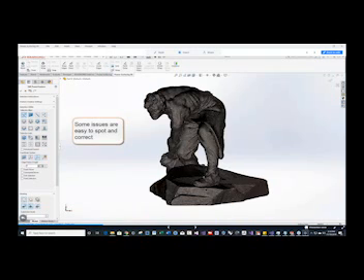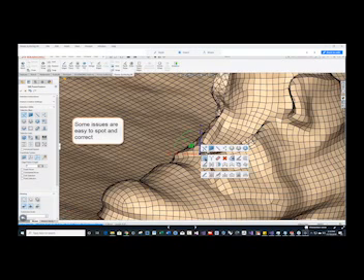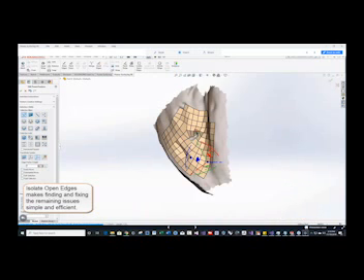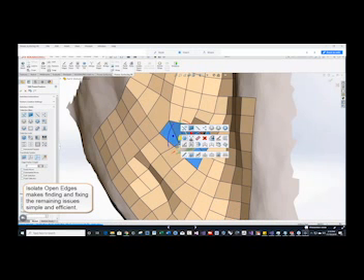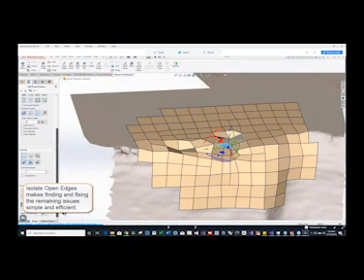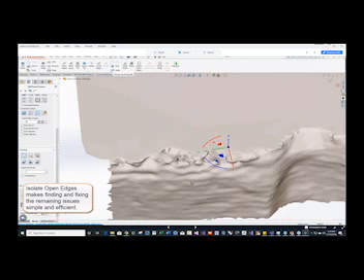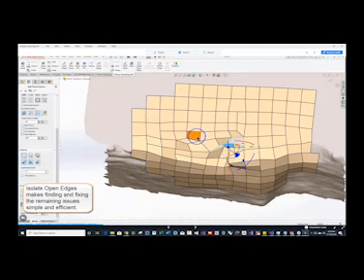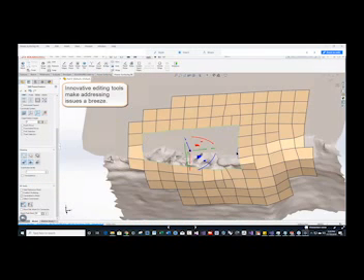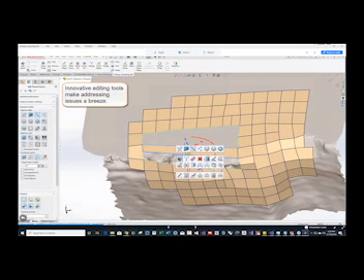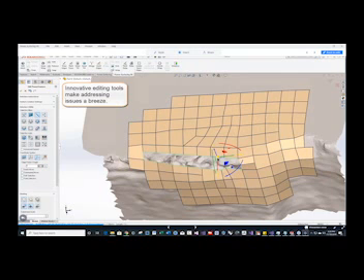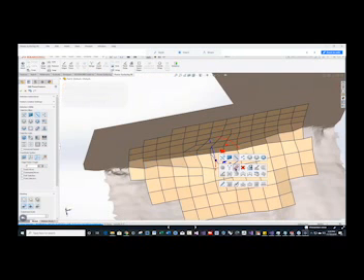Okay, here's how to clean it up. So we've done the quad wrap, and sometimes you can just fill the holes. Here's an example where we have some bubbling going on, like a little teeny hole there. And so we fill it up, and here's one of the bubbled edges where the scan is not real good. So we'll just delete that area. And you can see how quick and easy this is. Can you imagine trying to fix up that underlying mesh and get a nice shape like this? So you can see how we've been able to create a nice edge there.